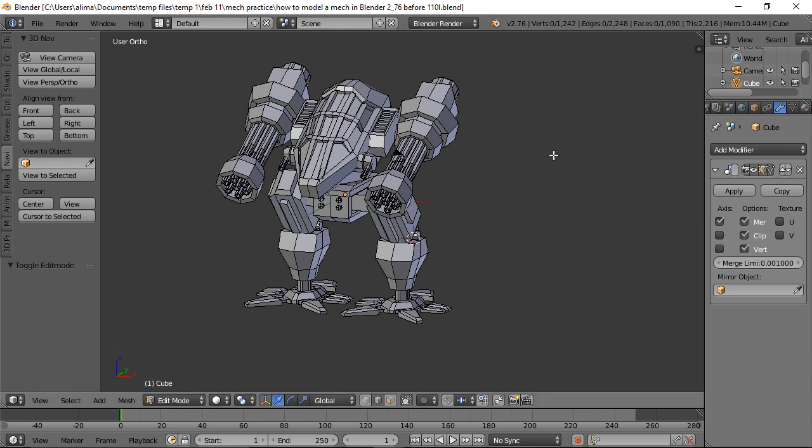Hard surface modeling is basically a fancy way of saying that typically when you work with organic shapes, you put something called a subdivision surface modifier on an object, and that smooths everything out, right? So when you are dealing with a mechanical object and you put a subdivision surface on something to smooth it out, you come up with the issue that because it's not organic, you want some pieces hard and some pieces soft.